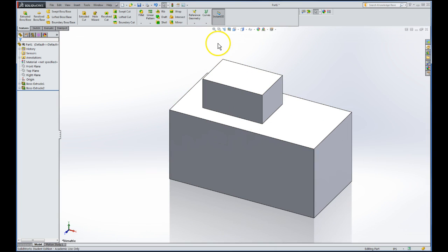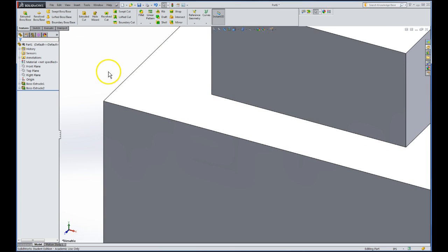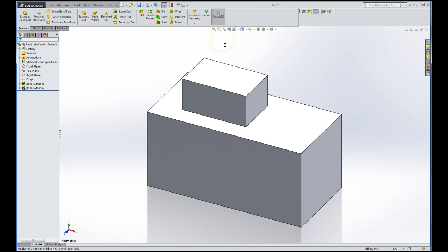I find zoom out is usually more conveniently done simply with the zoom to fit button. So that if I've got myself into a weird orientation, something like this, just zoom to fit is the quickest way to get back to where you can see it normally. We can also rotate the view, and that's also done with the middle mouse button or by clicking the mouse wheel.